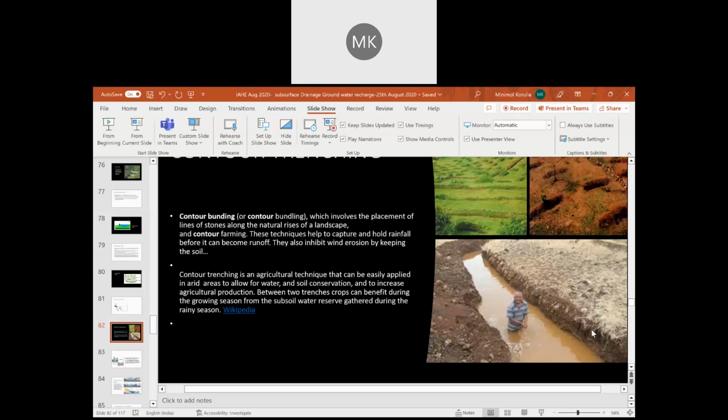We need to see the gradation of the soil, the apparent opening size of the geotextile if it is a drainage geocomposite, the permittivity of the drainage geocomposite, and the permeability of the aggregates if it is an aggregate drain, okay.